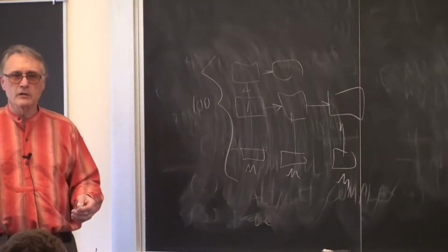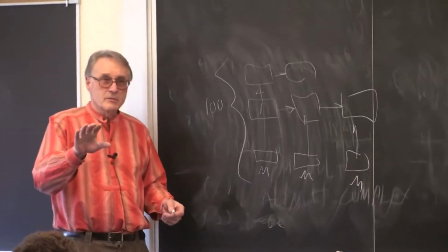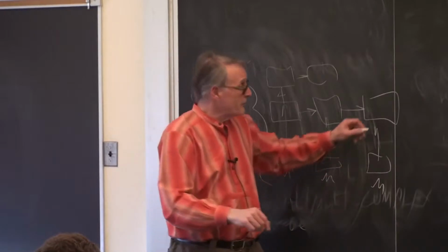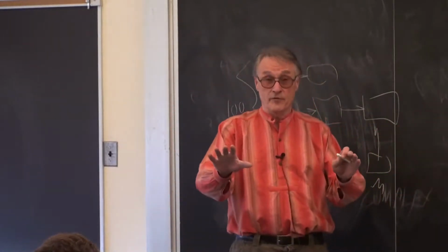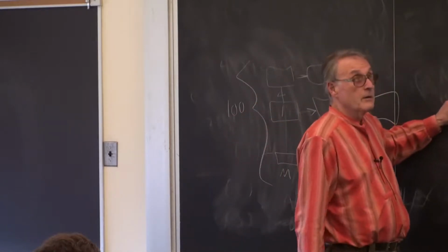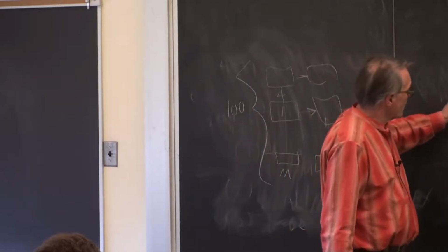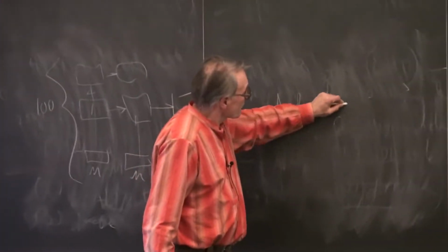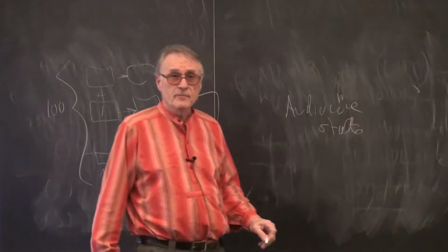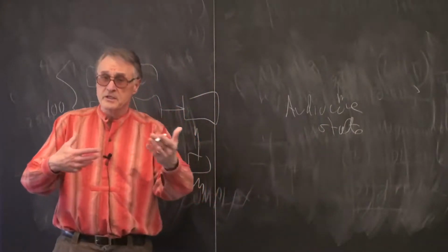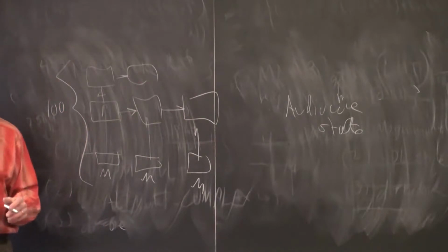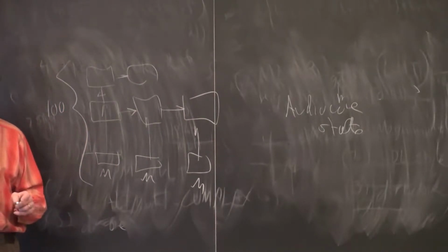We also need to talk a little bit more about simulation, because probably you're going to want to simulate, after you get the solver running, you simulate the solver first. But then you're going to have to simulate the audio core state machine, which, like the VGA state machine, does a dance with the audio core module on through Qsys.